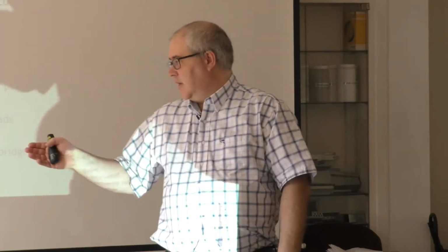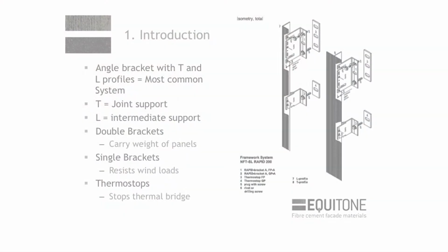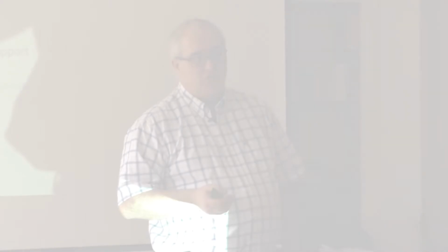So the thermal effect is transmitted through our panels, but it's the aluminium behind being many degrees cooler that is transmitting that, and you get that dampness. If you do get a phone call from the client or the owner saying the framing is showing through, I would suggest you delay it and visit the job in the afternoon, because once the sun comes up, it's gone. It's only condensation.